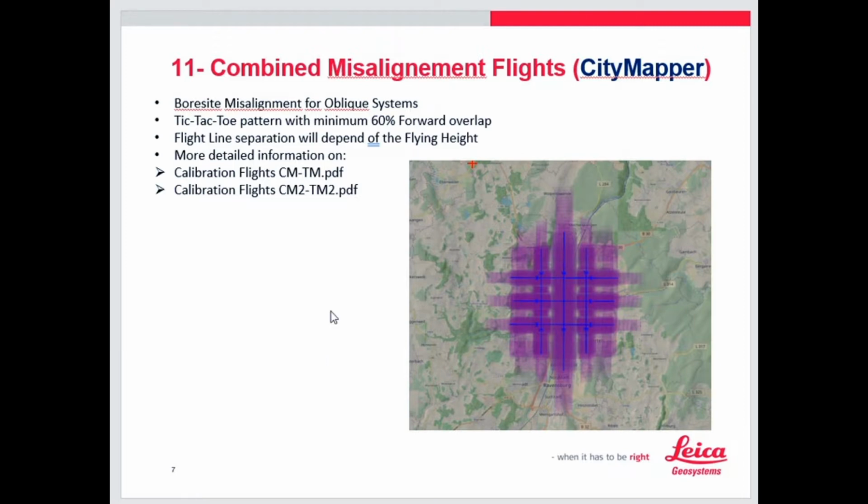Okay. So that's why whenever we're doing our flights with the production system, we're doing the different altitude, because we want to estimate the focal length. This is unusual. This is to estimate focal length, and this is when we do a full calibration, also Lidar. Lidar full, we are speaking about misalignment. Yes. Boresight. What we usually fly here is a full calibration, and for full calibration, we need to fly at 2 different altitudes for Lidar and for cameras. Okay. So it's the same flight plan, but we need both altitudes, and it will also estimate the focal length.